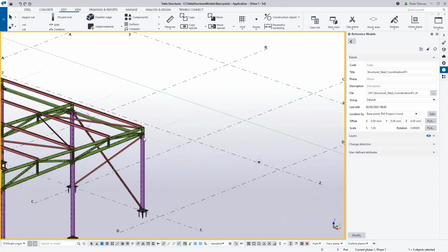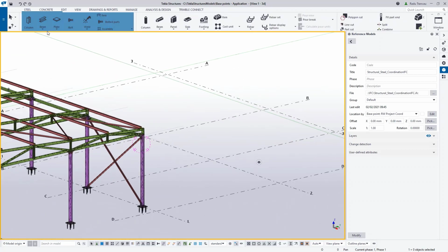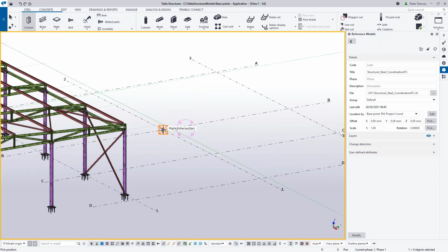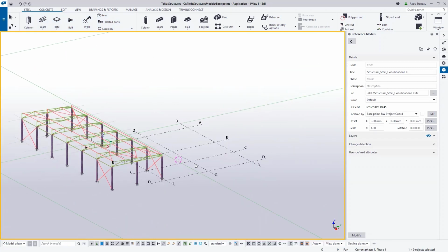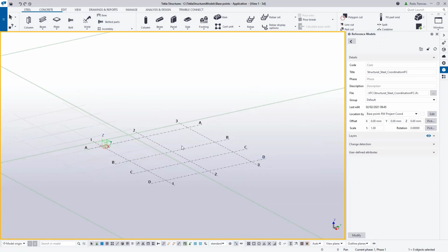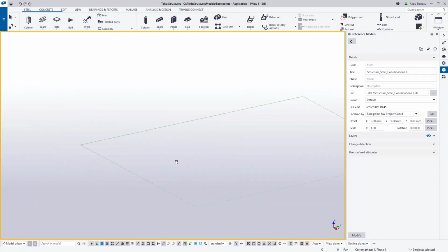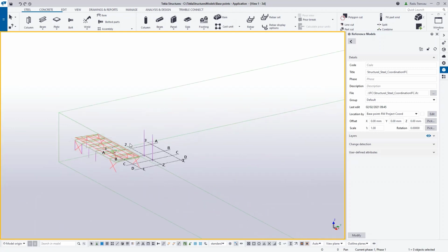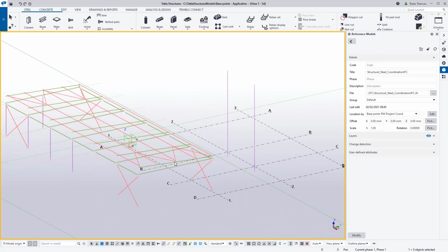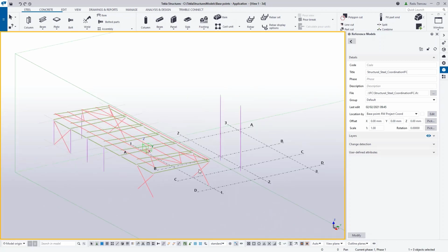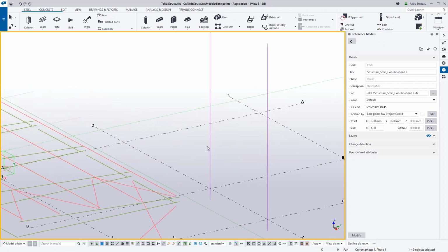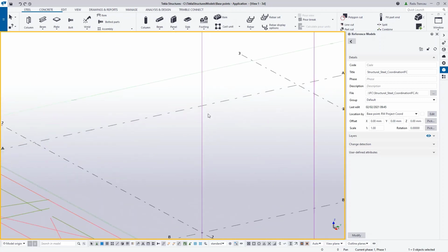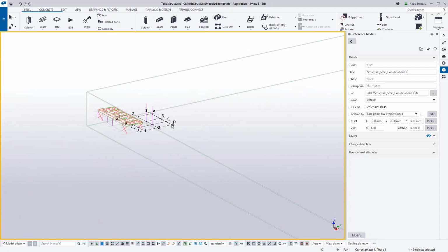Okay, so I will just try to quickly draw a column here and a column here. You can see it's not showing. So it's giving me the same glitches as before. That's one common issue with not exporting or importing the IFC close to origin and leaving this huge work area with objects which are very far away. A quick fix to this one.